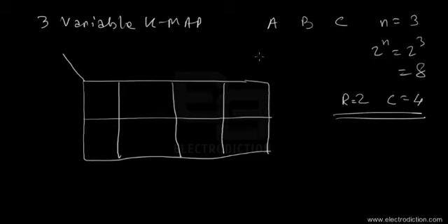Okay. So now since there are 3 variables, as we have assumed here, let's say they are A, B, and C. So let's just put A as the row element. You can see that the row is supposed to have only 2 binary values. That's 0 and 1. Now here we have 4 columns. So in order to put the values of these columns, we need at least 2 binary variables. So the binary designations would be something like 0 0, 0 1, and then you jump to the last one over here and put 1 0, and then come back again and put 1 1.